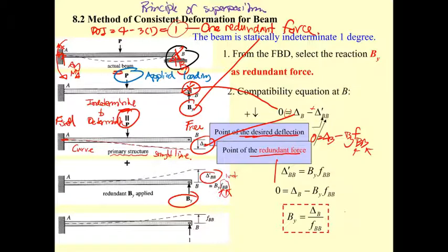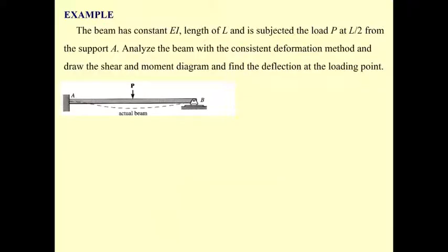Next, you use the force-deflection relationship in the compatibility condition to get B sub y. When you know B sub y, you can determine the reactions, the shear diagram, the moment diagram, and also the elastic curve.